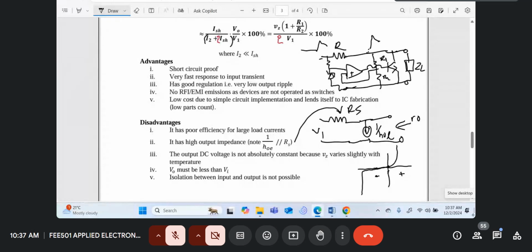So the slope of this curve over here will give you the dynamic resistance, because this axis is voltage, V diode, and this other axis here is current. So the slope of it will give you the dynamic resistance, and that dynamic resistance changes with temperature. Dynamic resistance becomes smaller, just like in the case of a normal diode, as the temperature increases. So this condition number 3 is not specific to only the shunt regulators, but any regulator whereby you have a Zener diode.